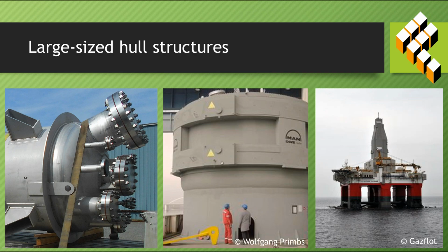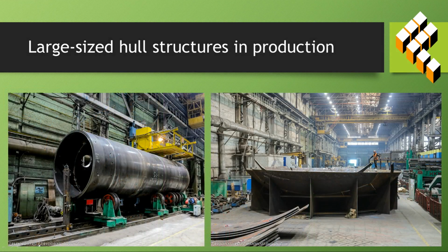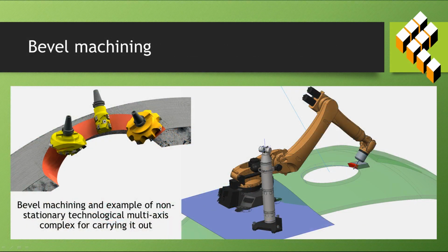The edges of hulls in the thick-walled hull structures where these parts are installed must be beveled to perform welding. A considerable amount of the bevel machining has to be performed directly on fully assembled structures in the slipway. To perform such works, non-stationary technological multi-axis complexes, abbreviated as NTAs, with computer numerical control are used. The main aim of this article is to develop an analytical mathematical model of the cutting forces acting on the edge surface of the hull structure.